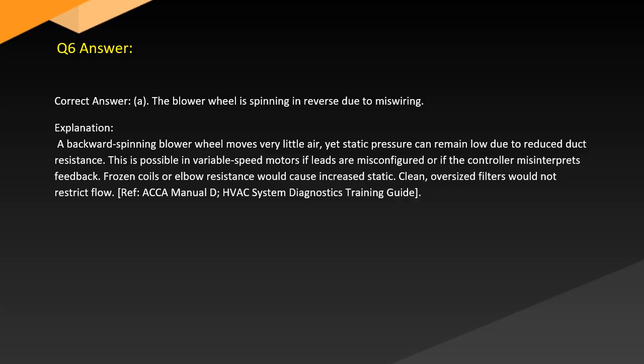Frozen coils or elbow resistance would cause increased static. Clean oversized filters would not restrict flow. Ref. ACCA Manual D. HVAC System Diagnostics Training Guide.